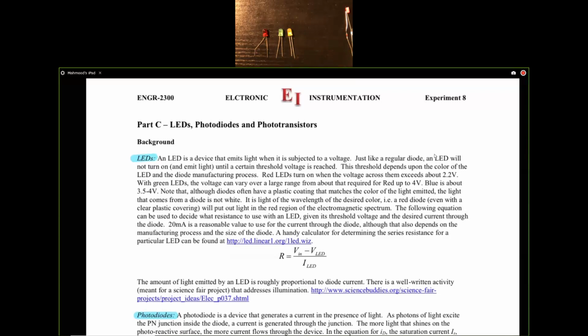So we don't want to do that. We want to have a resistor in series with the LEDs so that we are able to limit the current that goes through, and the voltage whatever we give is essentially split between those two components, a resistor and the diode. So in all our experiments you will see a resistor in the circuit that will help us protect our circuit elements.